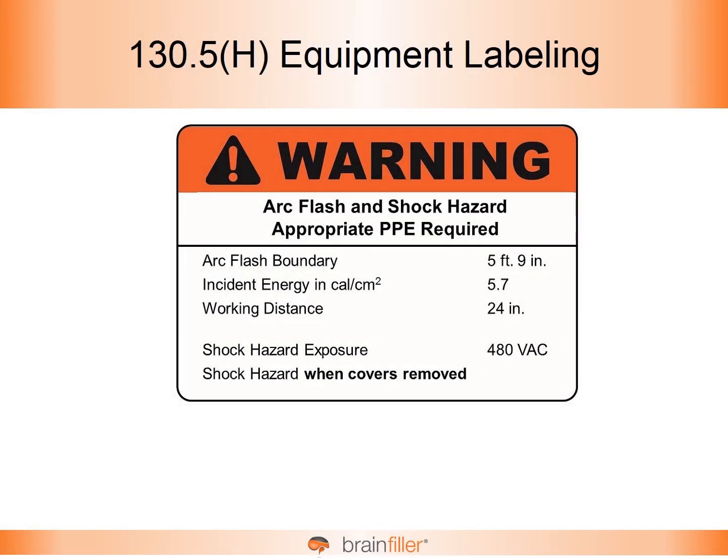This is a pretty typical arc flash label. Up at the top is the signal word, and signal words are defined in ANSI, American National Standards Institute, Z535. Warning is commonly used with the background orange. Orange actually goes with warning. And then there is the message panel that states arc flash and shock hazard, basically what is the problem.